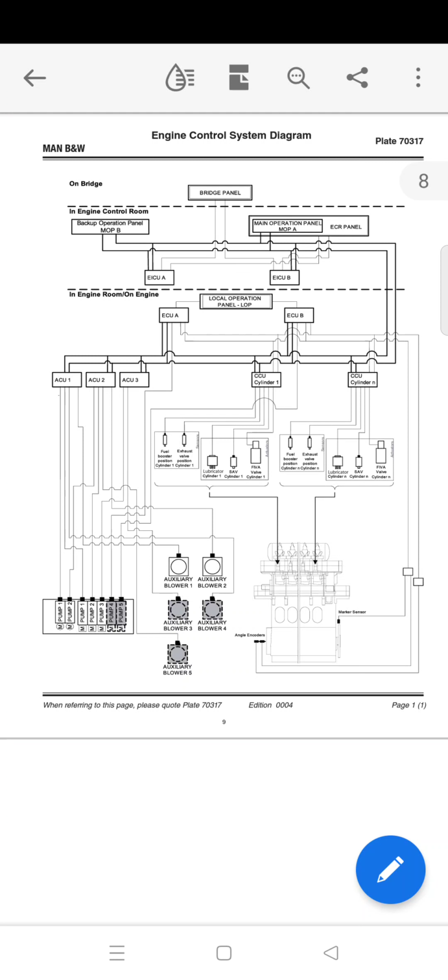MOP B is based on standard PC technology, with a keyboard, mouse and CD-ROM drive. So MOP B has connection with the Ethernet. Only MOP B may be equipped with an Ethernet card for connection to other systems such as COCOS EDS, computer controlled surveillance engine diagnostic system. Special care must be taken when connecting to a network of any kind to avoid viruses and worms on the MOP.